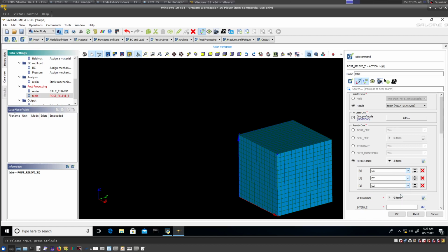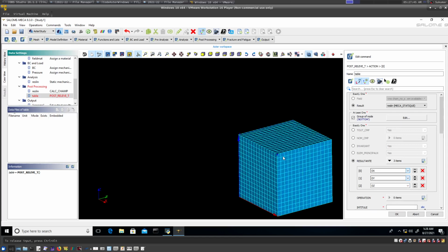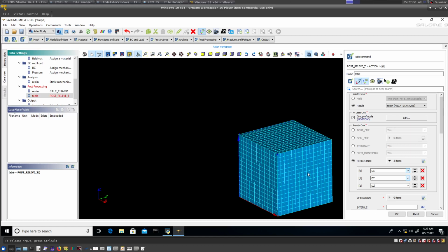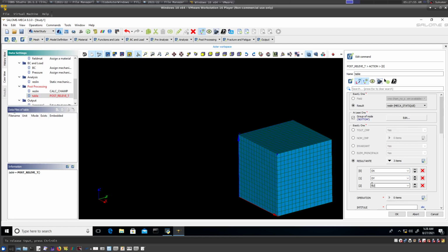And if it is a beam or frame element, I will also have moments. That's why here in this case an xx is there. Yes, an xx will be useful for shell elements, and in Code-aster we have three-dimensional shell elements also. That's why those forces are shown, but it is not relevant here. That's why I have not selected them.